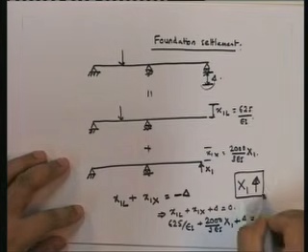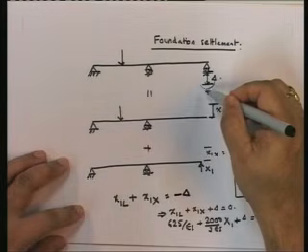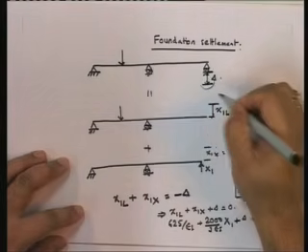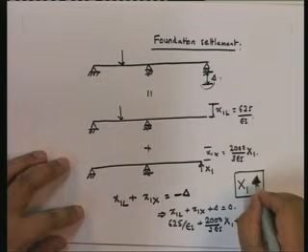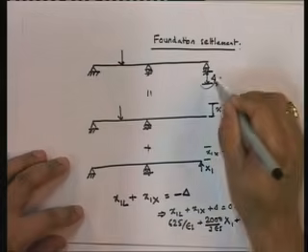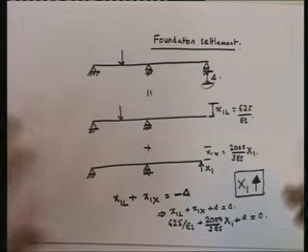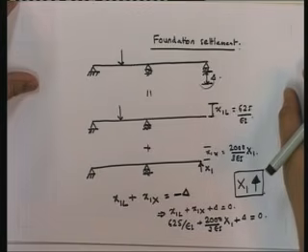And that makes sense because due to the support settlement, this is going to take up a much larger value of reaction, because support settlement causes a larger reaction to come up. Okay. So you see, foundation flexibility and foundation settlement actually do not affect the solution of the statically determinate problems themselves. All that foundation flexibility and foundation settlement both do is that they directly affect the compatibility conditions that you have. Okay?